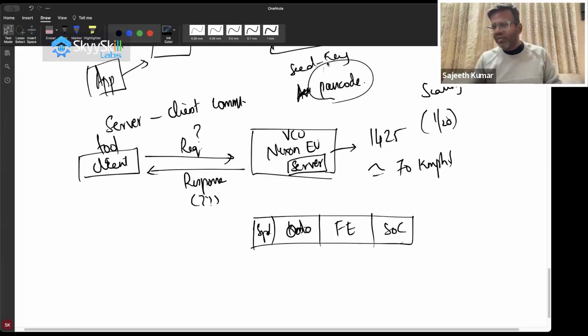From next year onwards, there is cybersecurity which comes, which means you will properly have a hash algorithm, and any message communicated over the CAN bus starting from next year, 2027 onwards, will be encrypted almost to the levels of what credit card and web-based transactions are encrypted, right? So you have a 256-bit encryption standard which is becoming mandatory on all vehicles. So that's cybersecurity, right? Once that comes in, things are going to be more difficult.